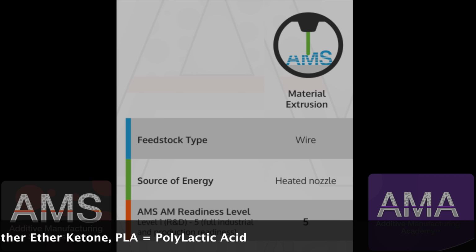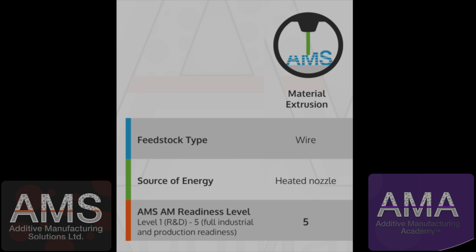Engineering materials, very high performing polymers, but also bound polymers where we maybe have a metallic or a ceramic component in the matrix, which is then used in a sintered post-process, allows us to make ceramic or ceramic infused at least, and sometimes relatively dense metal parts using this relatively low cost and accessible process.